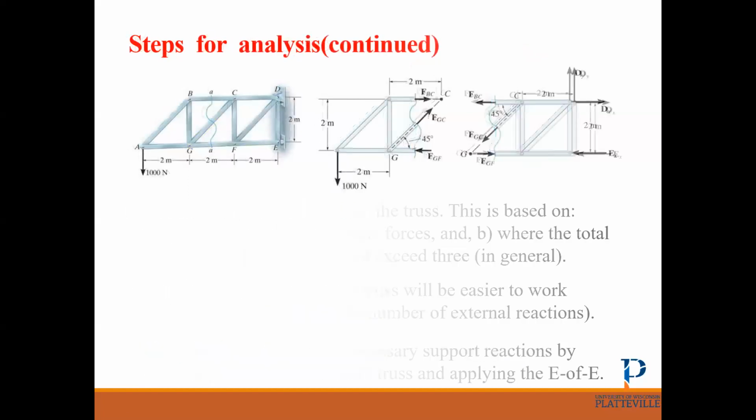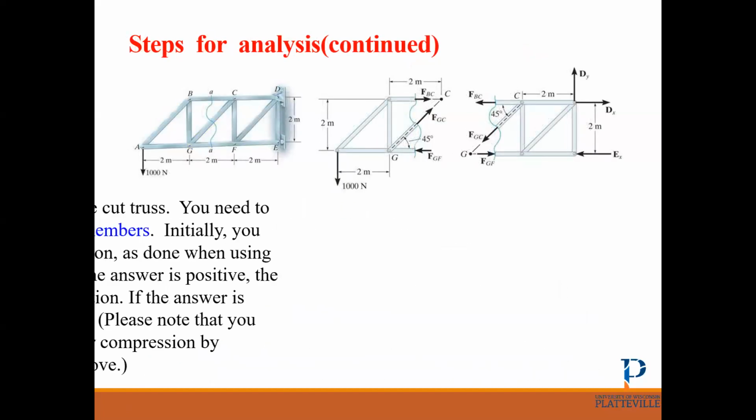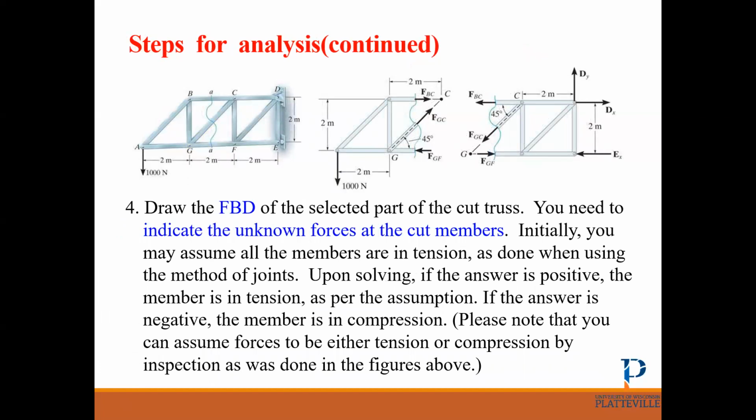All right, let's see what the next step is. After you draw the free body diagram, if you know which direction, you can put all these forces in that direction. If not, just assume all of them are in tension, and then if you get negative, it means they are in compression. Okay, now you are ready to use the equilibrium equations.